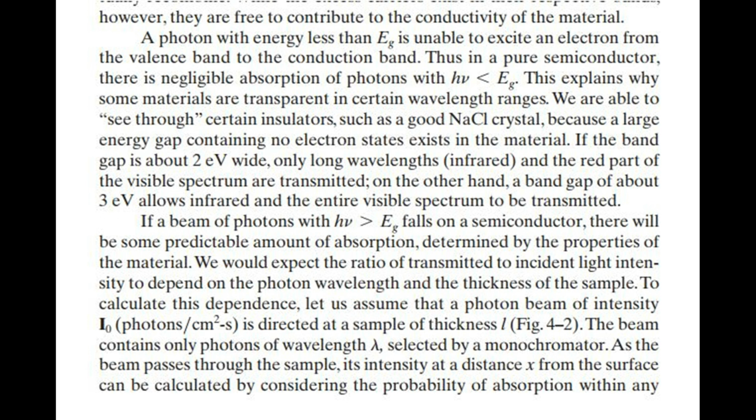falls on a semiconductor, there will be some predictable amount of absorption, determined by the properties of the material. We would expect the ratio of transmitted to incident light intensity to depend on the photon wavelength and the thickness of the sample. To calculate this dependence, let us assume that a photon beam of intensity I0, photons per centimeter squared per second, is directed at a sample of thickness L, Fig. 4.2. The beam contains only photons of wavelength λ,